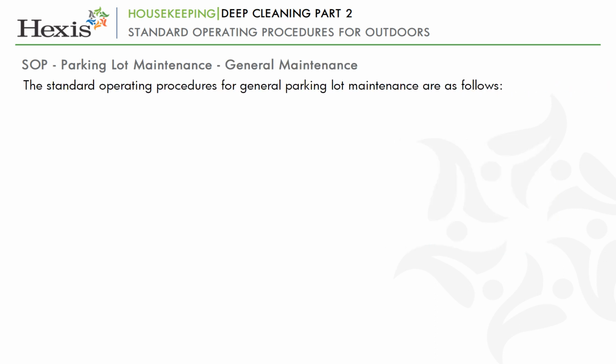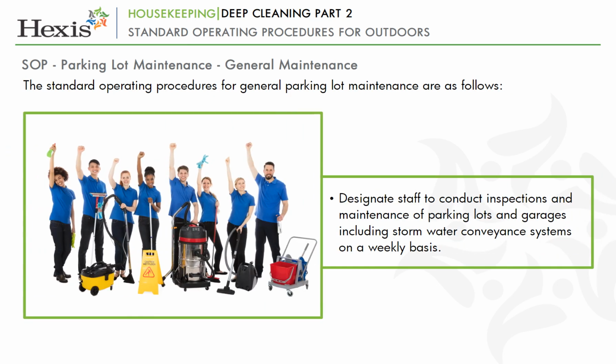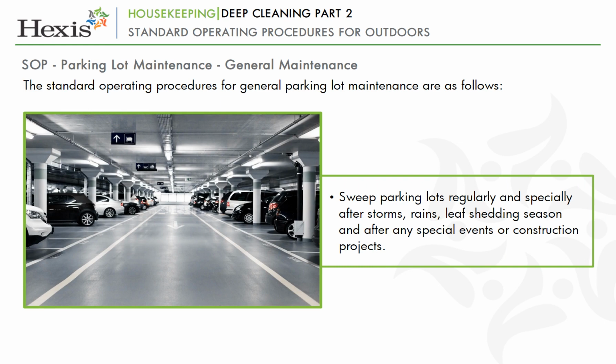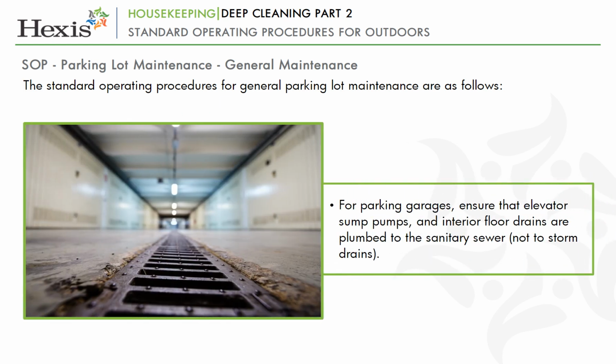The standard operating procedures for general parking lot maintenance are as follows. Designate staff to conduct inspections and maintenance of parking lots and garages, including storm water conveyance systems, on a regular basis. Suggested frequency: weekly. Sweep parking lots regularly and especially after storms, rains, leaf shedding season and after any special events or construction projects. For parking garages, ensure that elevator sump pumps and interior floor drains are plumbed to the sanitary sewer, not to storm drains.